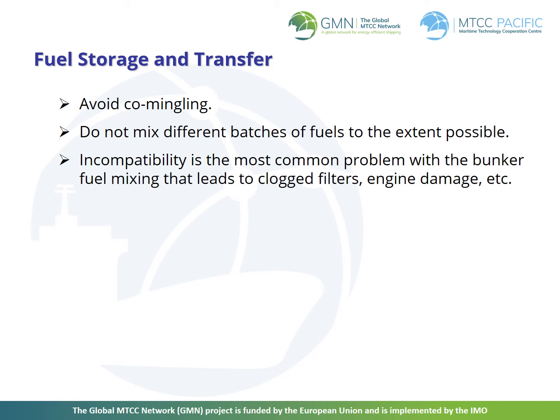The key points here are as follows. Avoid co-mingling. Do not mix different batches of fuel as far as possible. Note that incompatible fuels are the most common problem with bunker fuel mixing, which leads to clogged filters, engine damage, and other problems.